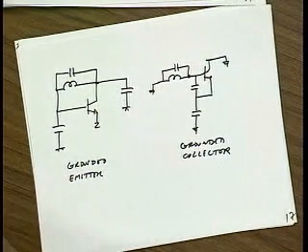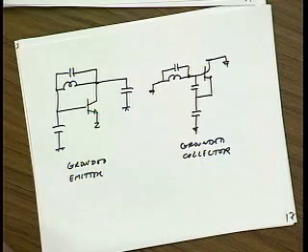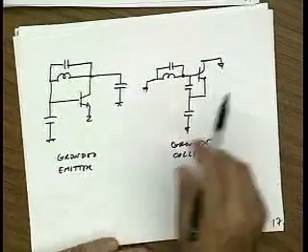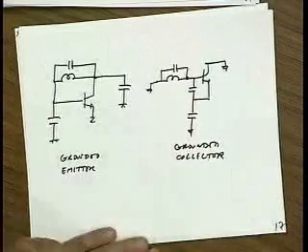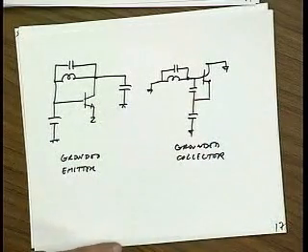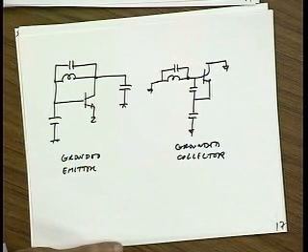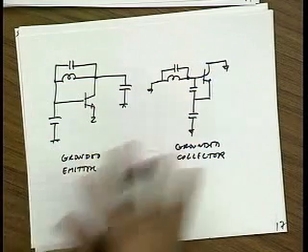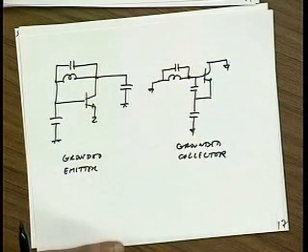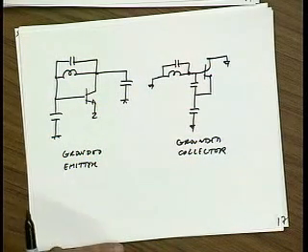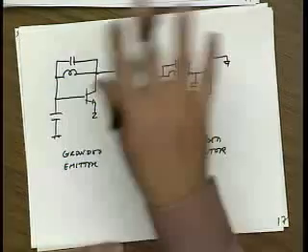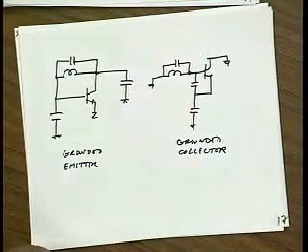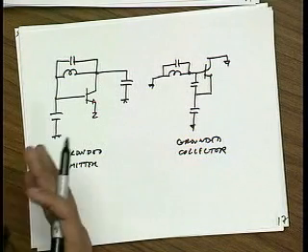What's leakage? LO leakage. So by definition, this is an oscillator, so LO is everywhere, right? There is no leakage. Oh, I see what you mean. That's actually a very good point. So let's defer discussion, because right now we're just talking about oscillators in general. Later on, we'll see, to build a robust oscillator, first of all, you'll probably go differential. So we could take all these circuits and turn them into differential equivalents to try to minimize basically supply noise and ground noise.